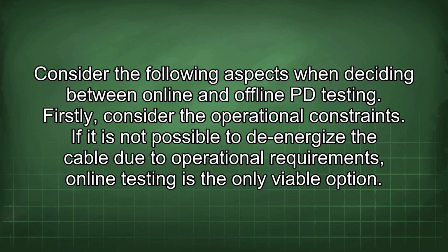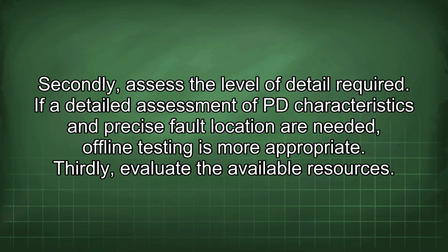If it is not possible to de-energize the cable due to operational requirements, online testing is the only viable option. Secondly, assess the level of detail required. If a detailed assessment of PD characteristics and precise fault location are needed, offline testing is more appropriate. Thirdly, evaluate the available resources.